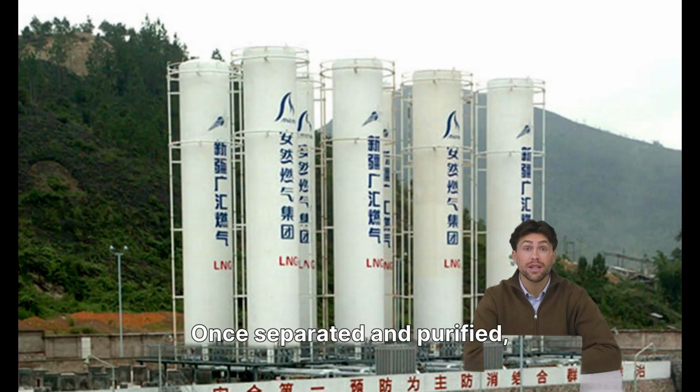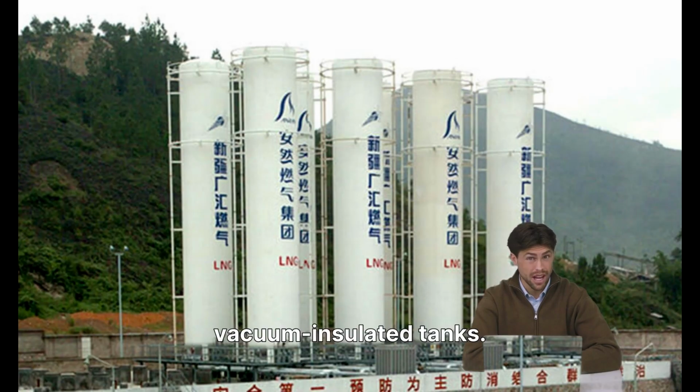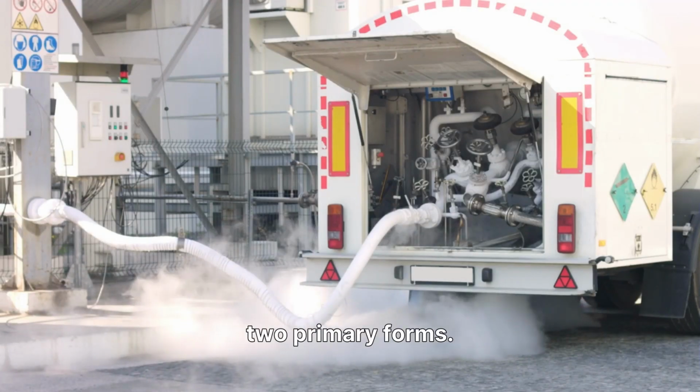Once separated and purified, the liquid oxygen, maintained at an extremely cold temperature of -183 degrees Celsius, is safely stored in large, specially designed vacuum-insulated tanks. These tanks are engineered to minimize heat transfer from the surroundings, ensuring the liquid oxygen remains in its cryogenic state for extended periods. From storage, the liquid oxygen is dispatched in two primary forms.